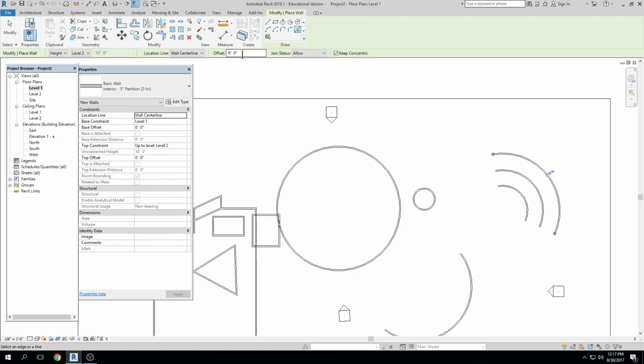So this is helpful for general drawing construction. There are things that you're going to want to, like if you want a hallway 3 feet, you can draw the hallway offset 3 feet from one side of the wall, right? But what this is really helpful for, and something that we'll talk about immediately next week, is if you have a CAD drawing and you are tracing over the top of the CAD drawing in Revit, right?